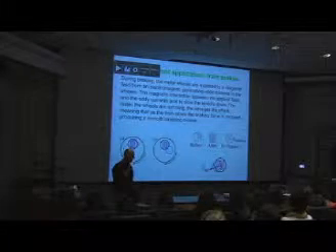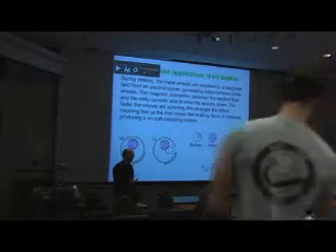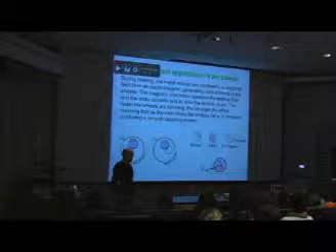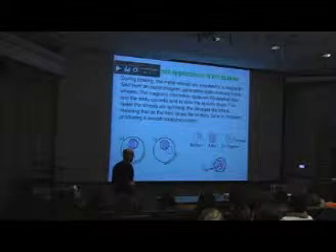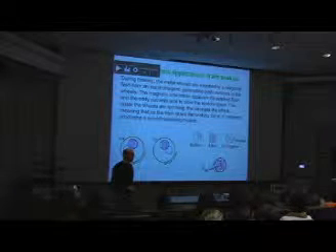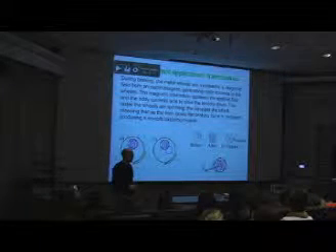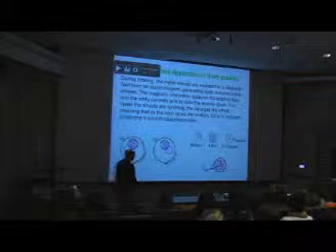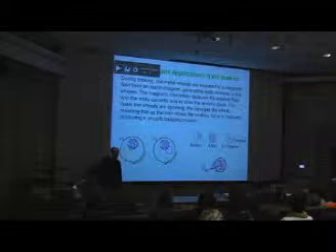Okay, and this is what Lenz's Law is all about. You're always going to get resistance to whatever's causing the flux to change. Okay, you can't use this to put energy into the system. It's great for taking mechanical energy out of a system, but you can't use it to go the other way. Are we okay with that? Okay.